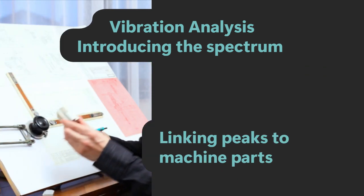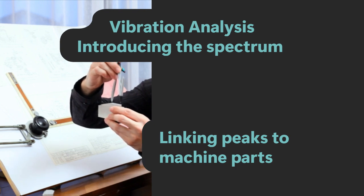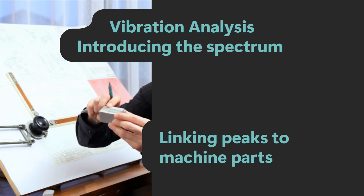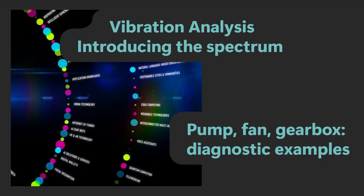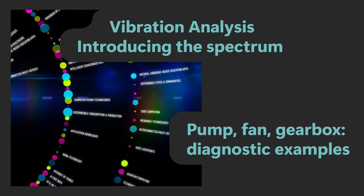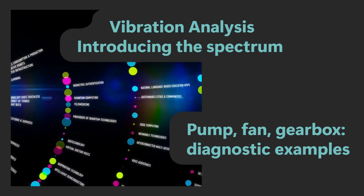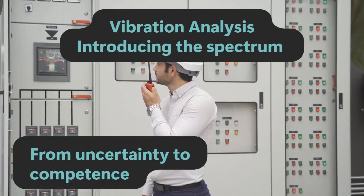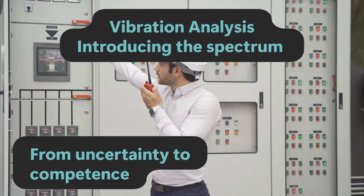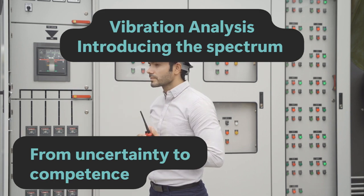Spectral interpretation isn't just science, it's detective work. By linking peaks to machine parts, engineers quickly diagnose problems. The documentary narrative guides viewers through case studies: a pump with imbalance, a fan with misalignment, a gearbox revealing gear mesh frequencies. Confidence comes with practice. As each spectral feature is explained, the viewer's journey moves from uncertainty to competence.